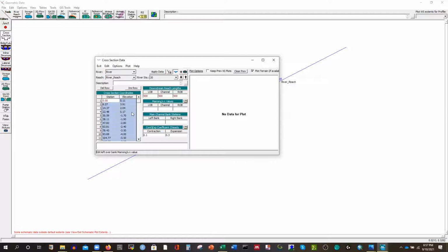So what will be the Manning's coefficient? We are giving the standard value 0.023. We can give that, and in the channel it is different, on the bank it is more than that. So in the channel I'm giving 0.020, and I'll use the same values for all of these sections because we are selecting a cross section reach that is mostly 3-4 kilometers, or up to about 10 kilometers, less than that.